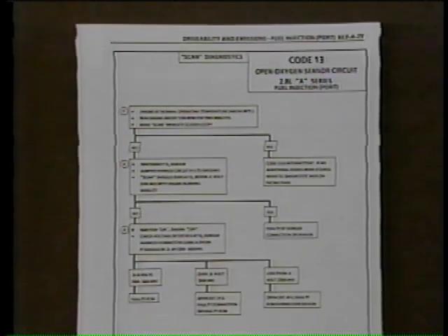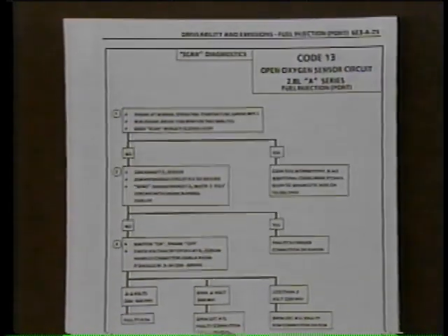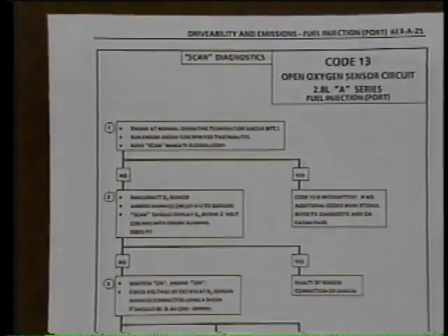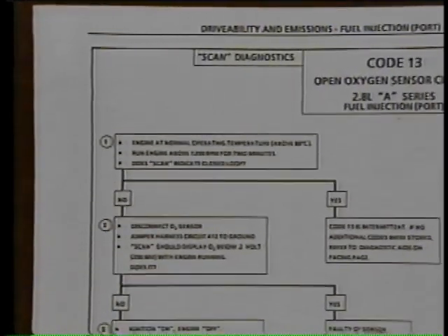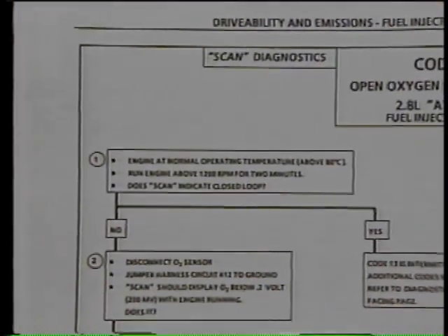So begin testing, starting with the lowest code number. As you turn to the code 13 diagnostic chart, you'll see the note Scan Diagnostics at the top of the page. This indicates that this particular diagnostic trouble code chart can only be used in conjunction with a scan tool.